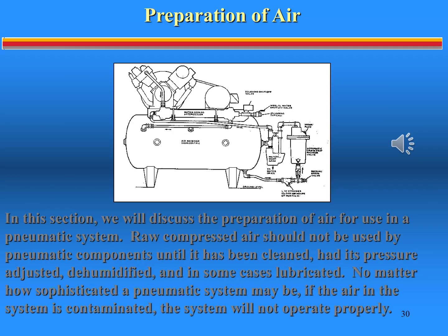Impurities in the compressed air, such as scale, rust, and dust, as well as the liquid constituents in the air which deposit as condensate, can cause a great deal of damage in pneumatic systems. These contaminants accelerate wear on sliding surfaces and sealing elements, adversely affecting the functioning and the service life of pneumatic components. As a result of switching the compressors on and off, pressure fluctuations occur, which have an unfavorable effect on the system operation. In order to eliminate these effects, compressed air preparation is needed.